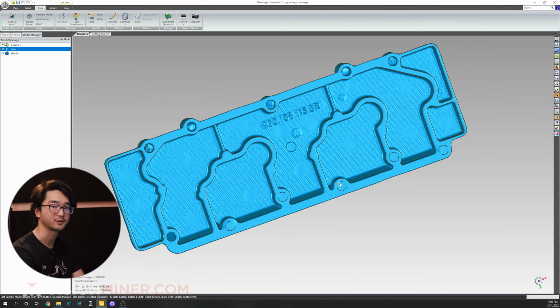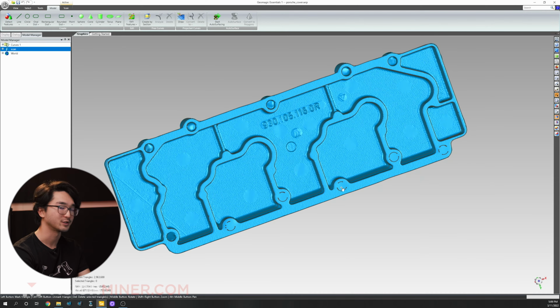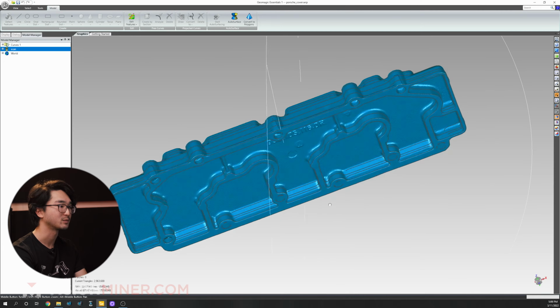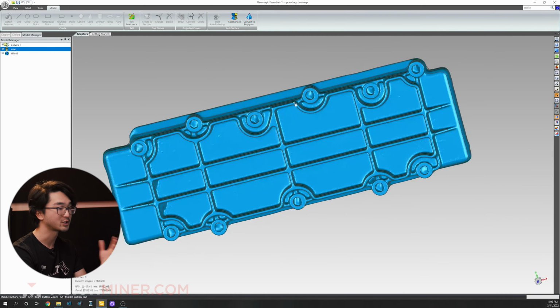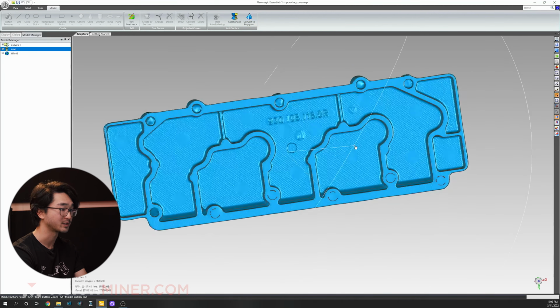with this surface model. First thing I'm going to do is go to the Model tab, and then on the very right, you'll see the autosurface tool, and I'm going to click Start Autosurfacing. And that basically tells me that the file that we see here needs to be perfect because we shouldn't go back into the polygon mesh.